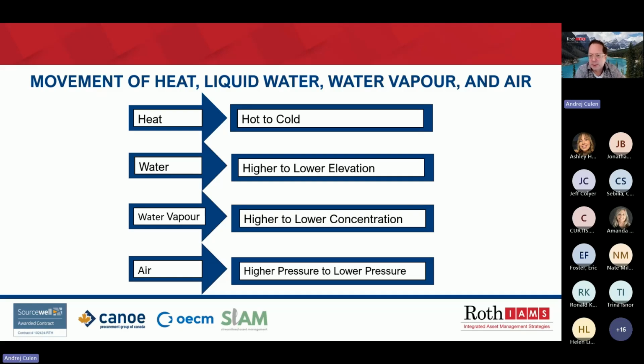Firstly, perhaps the most damaging is water. Water can rot the envelope, and if not caught or detected early, can continue behind the envelope and cause hidden damage to the structure below. Water flows, governed by gravity or capillary action, from higher to lower elevations. As often described, water will find the quickest and easiest path of least resistance to the ground.